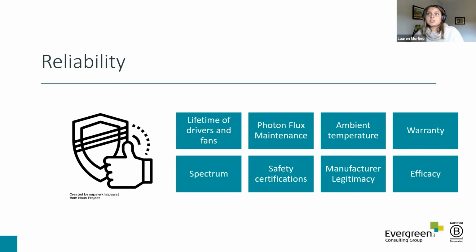DLC gathers information about really important product performance testing. As I mentioned, the products on the DLC list are tested by accredited labs throughout the country. For example, test data is reported for the lifetime of drivers and fans, which is important because these are the most common points of failure in these LED systems.